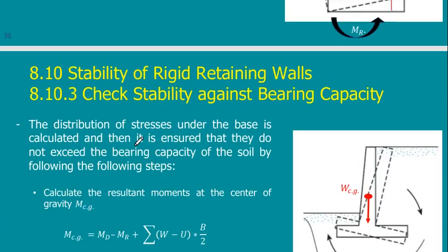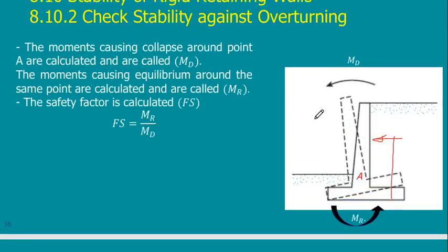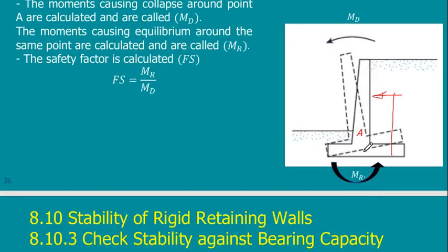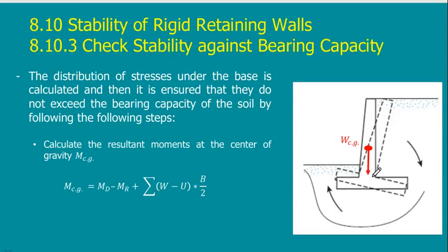There is another check for the bearing capacity, and I always say that it is not the most important one. The most important one is sliding, then overturning. The bearing is not very important because calculation-wise it is very complicated. But of course you can do it with a computer, but I'm speaking about my exam, I'm speaking about our courseworks.